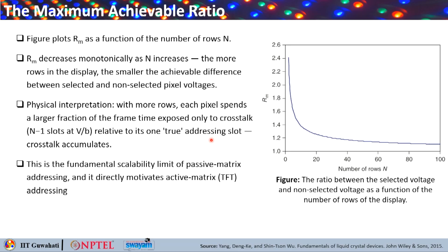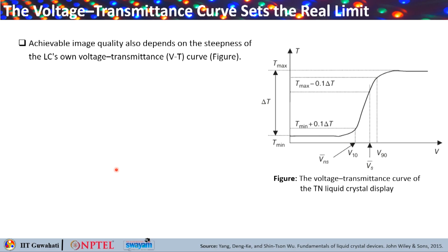So this is the fundamental scalability limit of passive matrix addressing, and that is why people got motivated to move towards active matrix TFT addressing. This particular slide connects the electrical drive scheme analysis of the last several slides back to the liquid crystal material's own optical response. The figure shows the voltage transmittance curve.